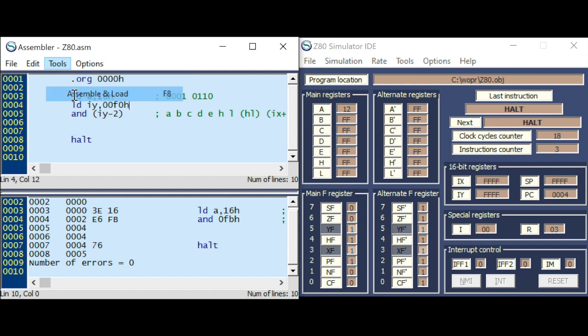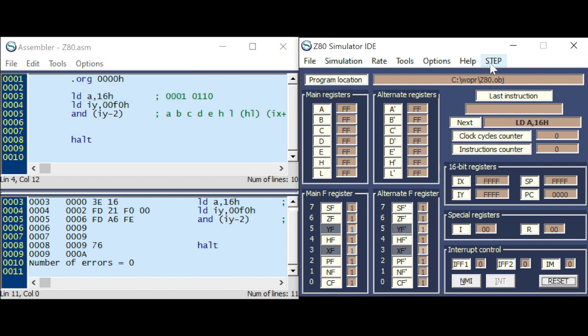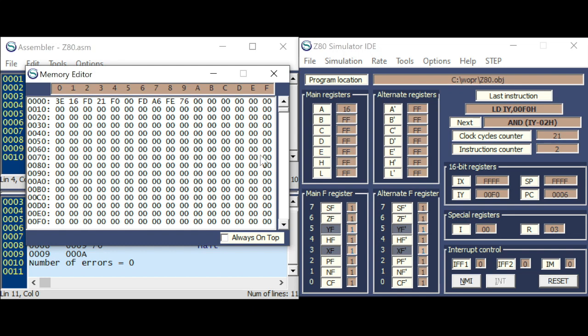So accumulator is loaded, IY is set. This is IY -1, -2 at address EE, and I will specify F0, so I'm cutting the 4 lower bits, and the result is 1, zero flag is 0, and the parity flag is 0 because there's only one bit.